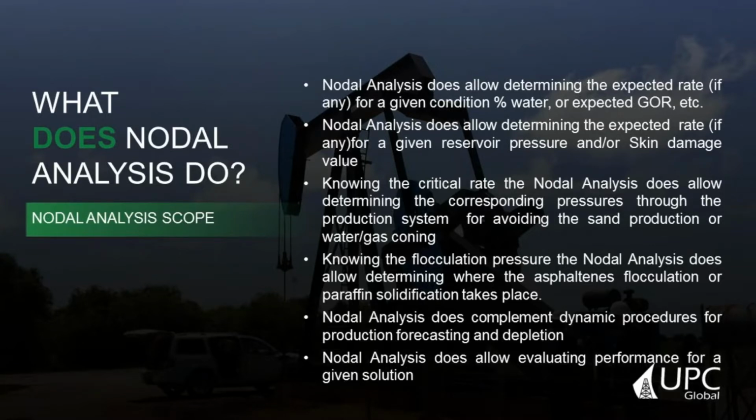Well, nodal analysis does allow determining the expected rate, if any, for a given condition of water percentage, GOR, etc. It allows determining the expected rate, if any, for a given reservoir pressure and/or skin damage value. Knowing the critical rate, it allows determining the corresponding pressure through the production system for avoiding sand production or water or gas coning. Knowing the flocculation pressure, it allows determining where the asphaltene flocculation or paraffin solidification takes place.